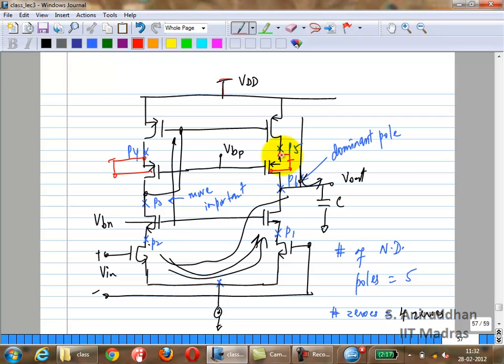Body effect is reduced. GMBS effect becomes less. Threshold voltage doesn't change. But would you want to do this? It seems like a no-brainer, right? For the PMOS, in any case, you want it to behave with a well-behaved VT. Would you do this?